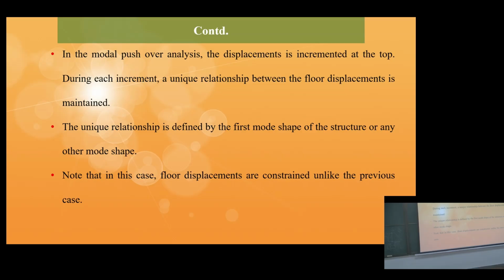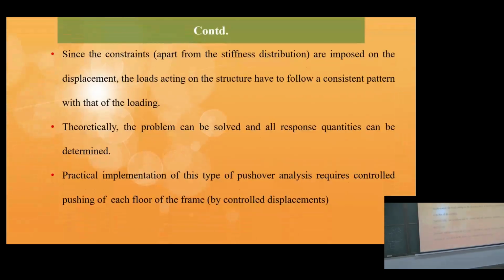Note that in this case, unlike the previous case where you gave only the top displacement and allowed the others to take values freely, constraints apart from the stiffness distribution are imposed on the displacement. The loads acting on the structure have to follow a consistent pattern with that.